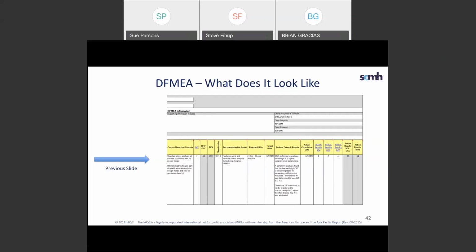So it's really intended to be a relative risk assessment. As we mentioned earlier, severity in and of itself is also a technique used to define mitigating actions because of the high consequence and impact to customers. Also, severity times occurrence, severity times detectability, those are also good ways of interpreting a DFMEA. So RPN is obviously useful, but it's not the only way to assess relative risk and mitigating actions.